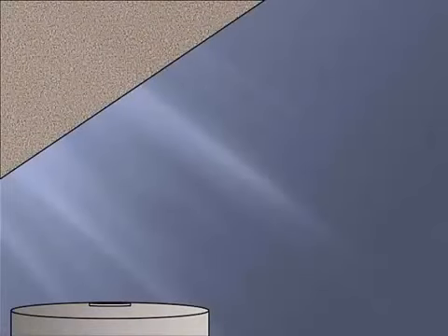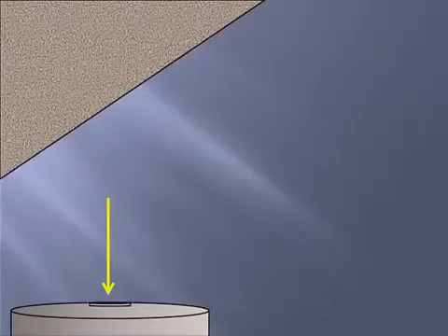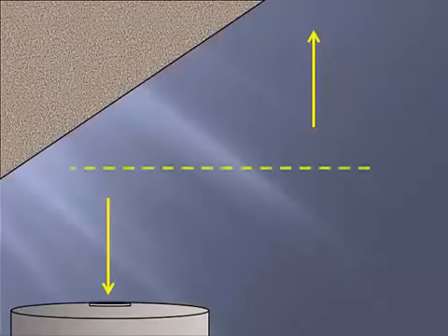We're going to start today's lesson imagining a tank at the lower corner of the drawing. We have an obstacle above it, and the objective is to create a piping system that would allow us to start at this position and pipe up to this location. So naturally, we're going to use some pipe and fittings to create an offset approximately at this location.